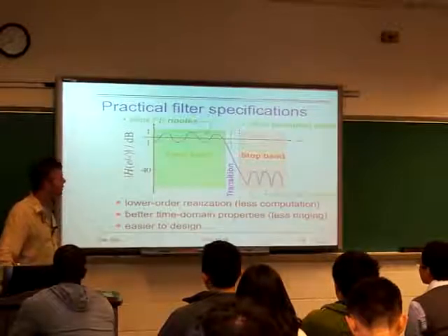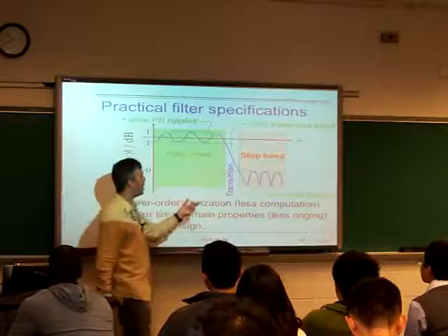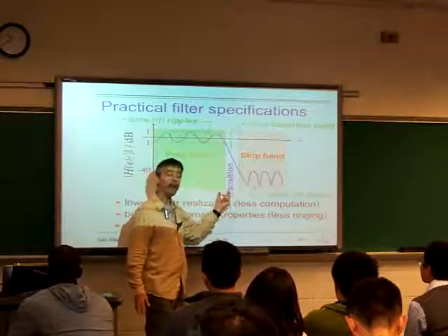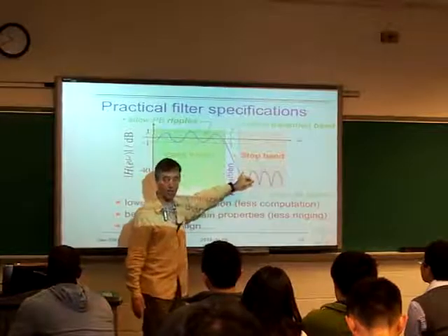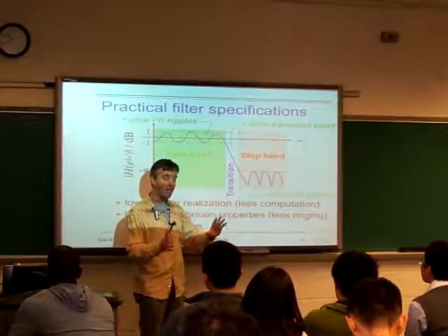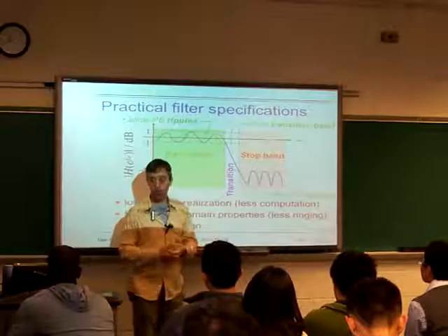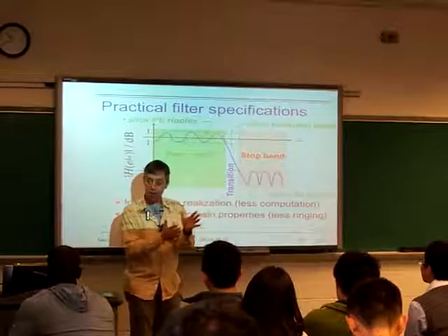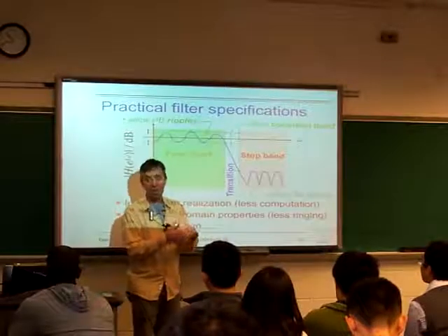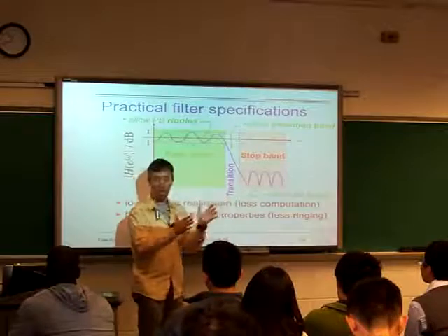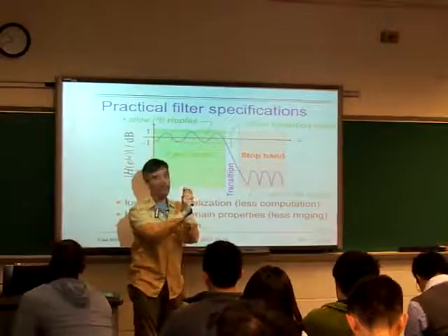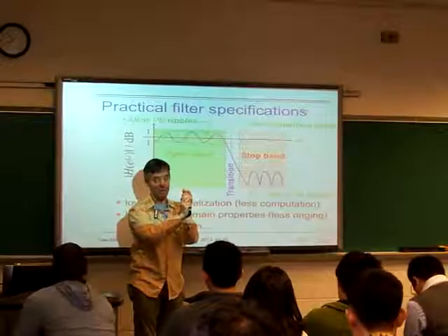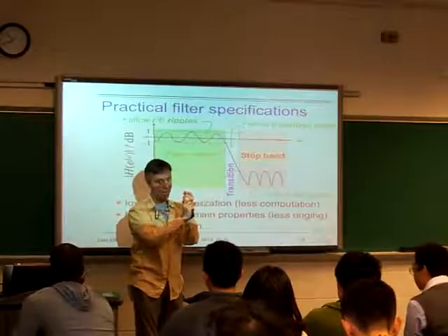Right. So with the transition band, all we're saying is, we recognize they're going to be separate frequencies for the edge of this pass band and the edge of the stop band. Now, if we have a design procedure, we expect those to be parameters. And so we can say, I want them to be really, really close together, or I don't mind, they can be far apart. If these are parameters, you can set them where you want them to be. You can try and set them to be the same frequency, although typically that's going to get you in trouble.